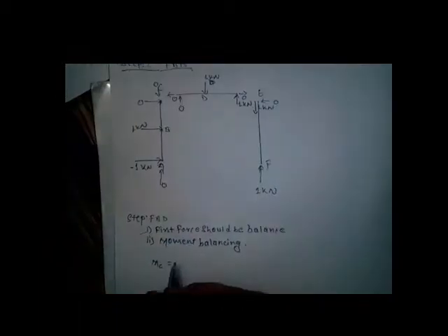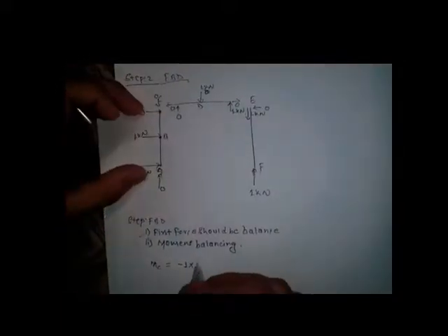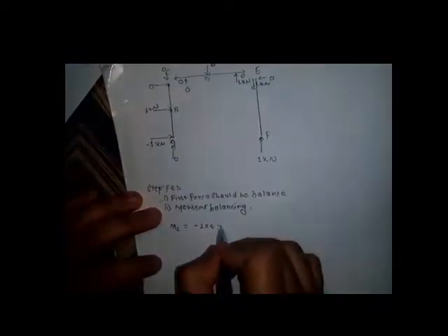At point C, due to the load of -1, it will be an anti-clockwise moment at C. That means C is rotated anti-clockwise. That is now -1 into this whole distance. This whole distance is 4, as it is given in our structure. You can see clearly here this distance is 4, and this is anti-clockwise direction, and due to 1 also it will be an anti-clockwise direction.